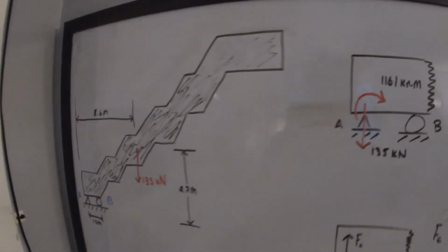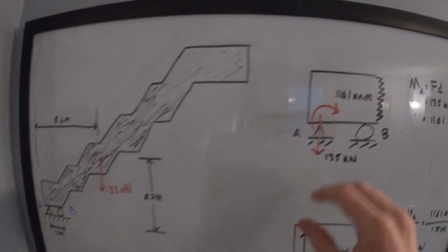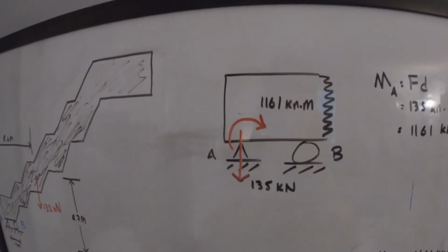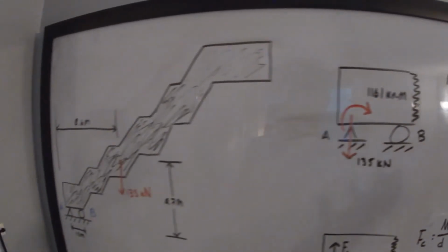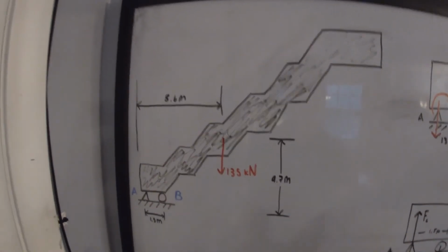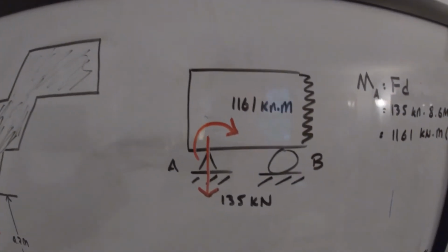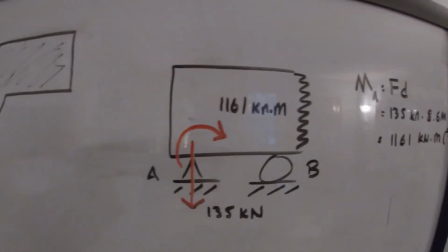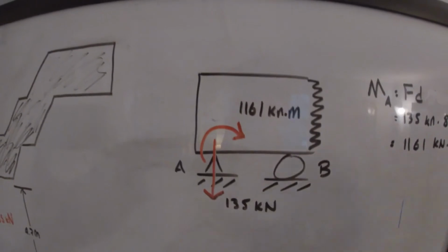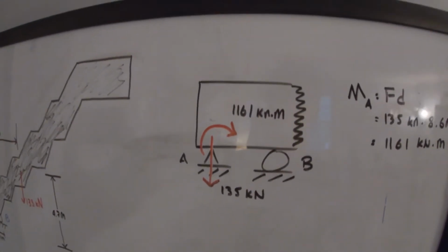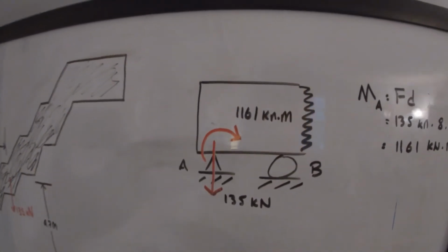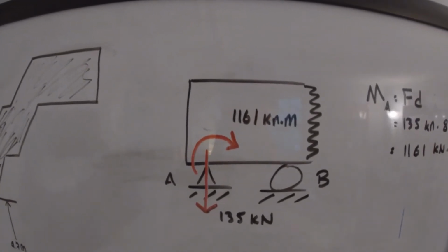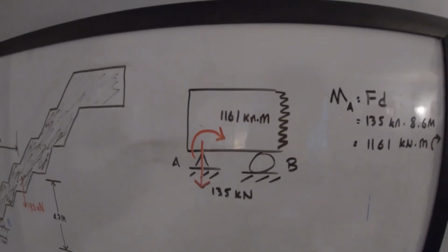So our equivalent force couple system at A is going to look like this. Again, this loading here and that loading here are identical. They're the same thing. It's an equivalent force couple system. So we've replaced this loading entirely with this loading, and it gives the same exact effect. And that's the beauty of these types of problems, because we can take a system that has a lot of different forces all over the place and summarize it with one force and couple. That's just simpler for us to deal with.